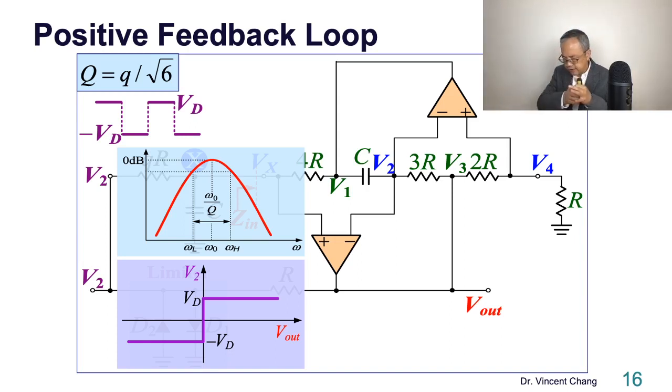So think about this. With the concept of Fourier series, a square wave is the infinite summation of many, many sine waves, and you send this into a bandpass, the output is still messy. But let's assume the Q is very high, which means what? Which means the bandpass is highly selective. Select which frequency? Only the frequency component the same as the fundamental frequency, the same as the center frequency, can get the maximum transmission. The rest of the harmonics will be attenuated greatly, right?